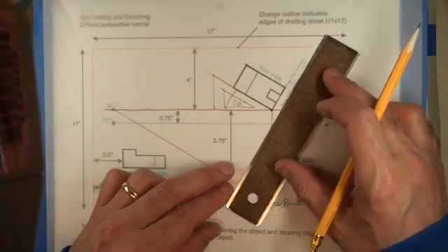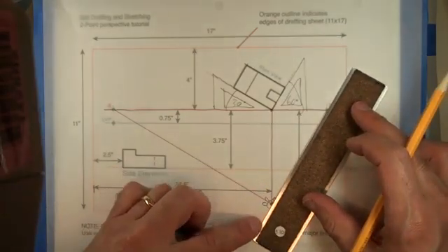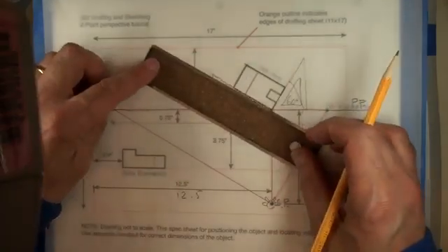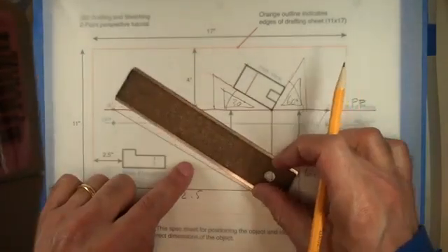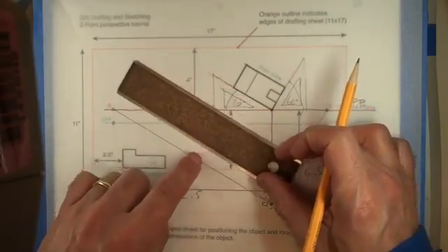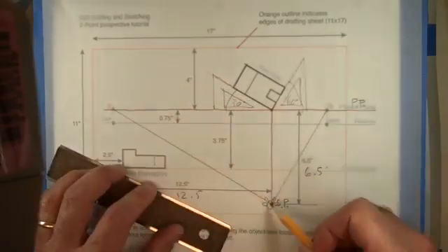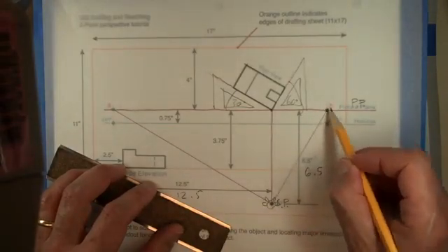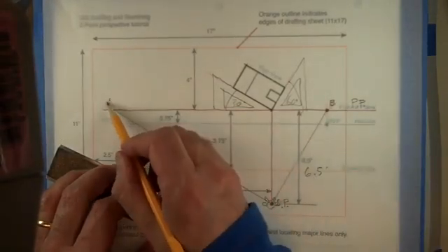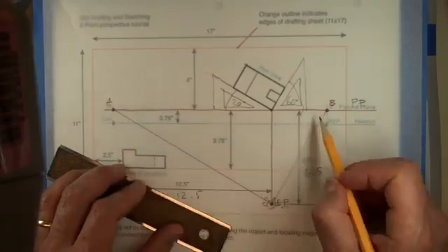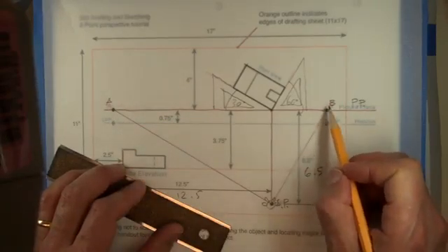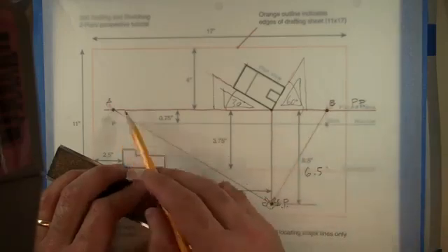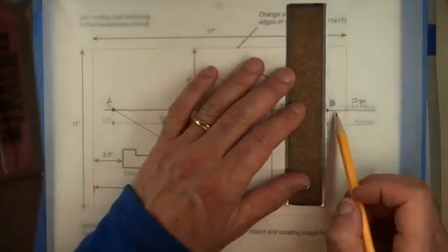So therefore this line here is parallel to this line. Let's say the right side of the object is parallel to this line that we're going to draw, and the left side is going to be parallel to this line that we're going to draw. Like that. And when those two lines from the station point hit the picture plane, we're going to call these points A and B. And let's just say right away that those are the only times you're going to need them. You kind of have to forget about them later on. When it reaches the picture plane, they come down vertically.